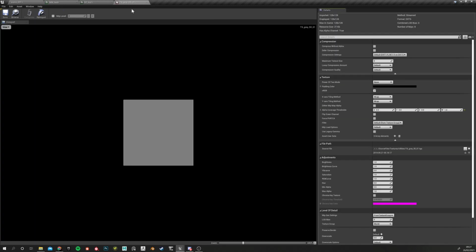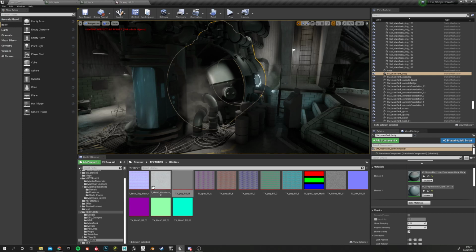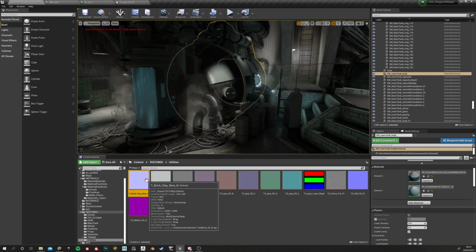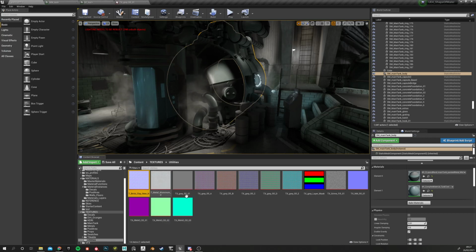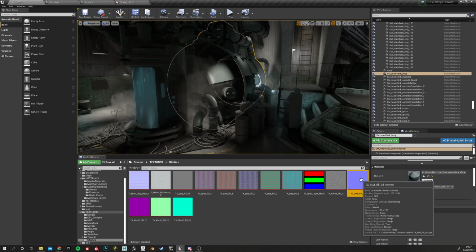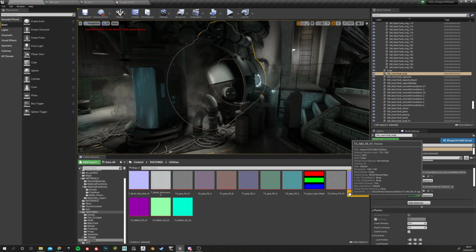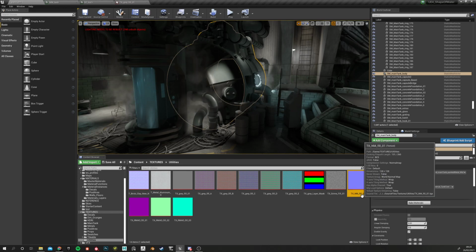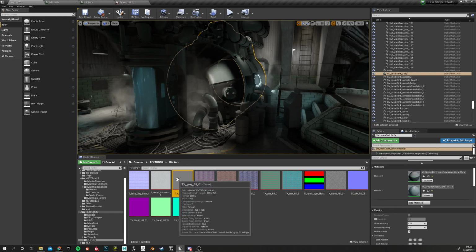Okay, so what you can do is create them. It's very simple. This stuff is just Photoshop, and I created this one as well, and this one is 2K, but I just had it because I wanted to. For my normal, for example, I create the same: just a normal with red, green, and blue, 0.5 on red, 0.5 on green, and 1 in blue, at 128 by 128, and I name that underscore text underscore nm underscore field. Okay, so I'm going to use this one, gray field.